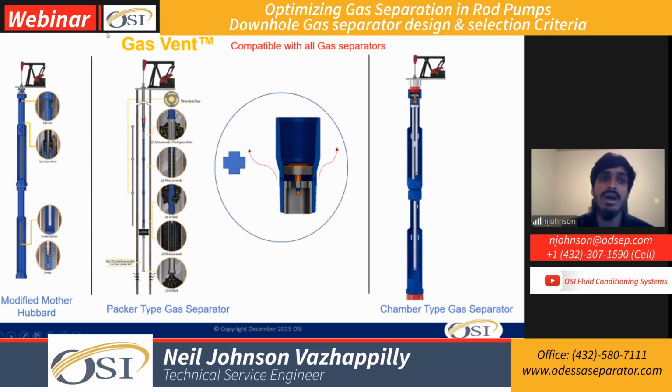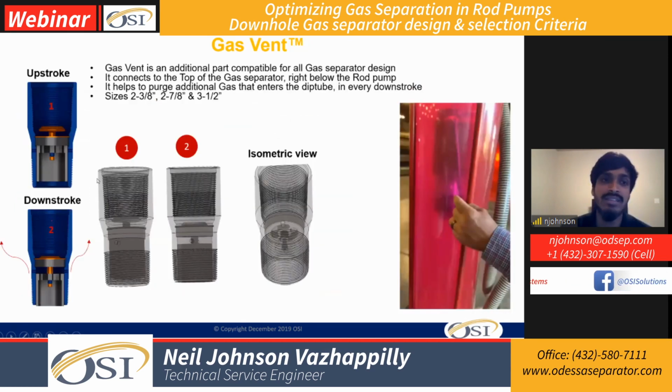So this gas vent system is an additional valve system which opens and closes, and it's compatible with all three types of gas separators that I've just mentioned. It's compatible with the modified, the packer type, and the chamber type, and it's installed right above all of these separators, below the seating nipple. Now, the way it works, I'll show you this video in a bit, but just like I mentioned, it's a valve system.